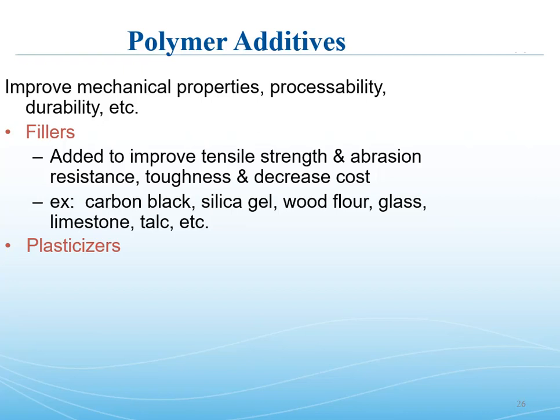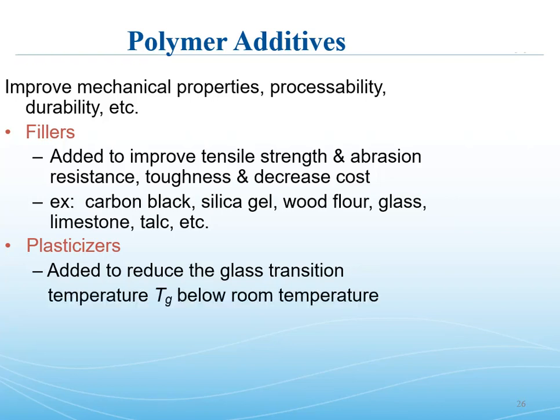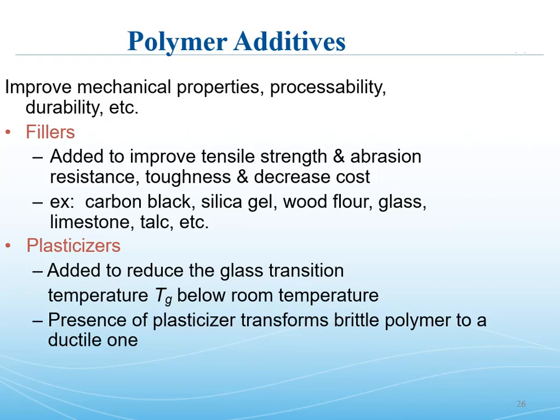In the case of thermoplastics, it can literally allow those chains to slide right past one another and greatly reduce glass transition temperature and tensile strength both. So again, if you have a polymer that's very, very brittle, adding a plasticizer and allowing some amount of chain slippage will give you fracture toughness and sometimes even a bit of ductility.